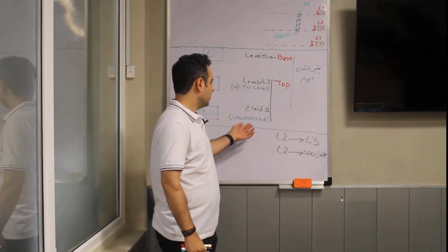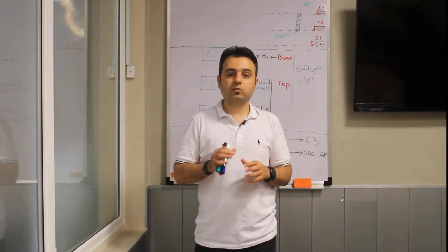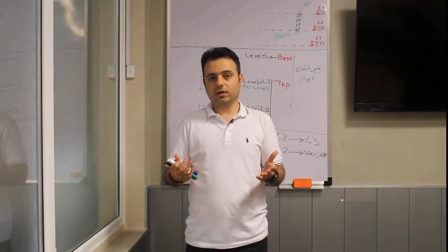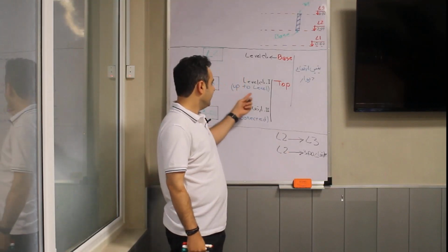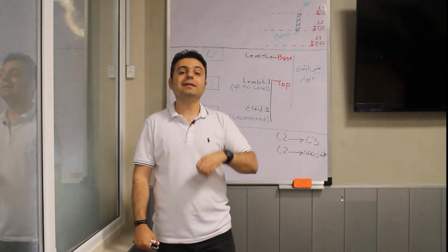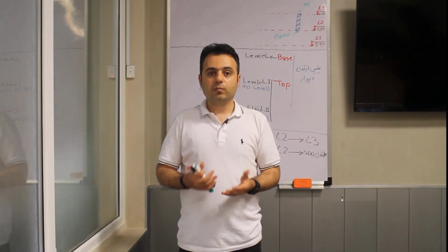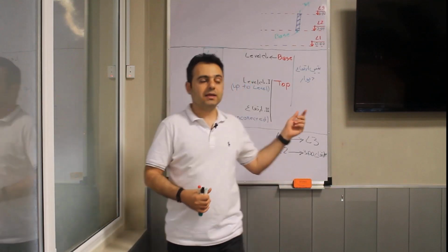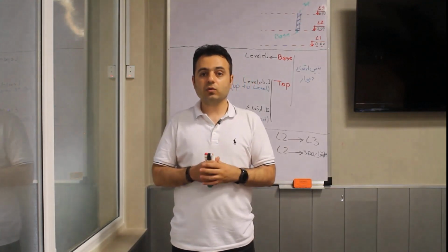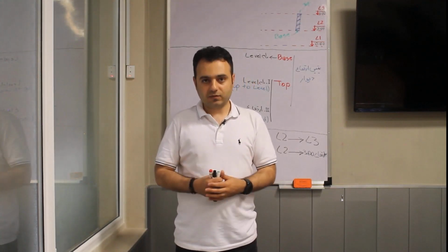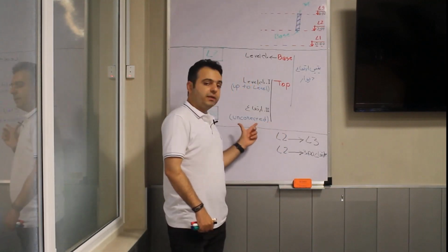But in the unconnected method, we need to go and select each wall one by one, and we might also make a mistake. So, choosing up to level as a method is not just an option here, alright? It's actually a must, a necessity. You have to do it so that we can use the options that Revit has for us, the intelligence of Revit itself actually. It's better to say it this way.